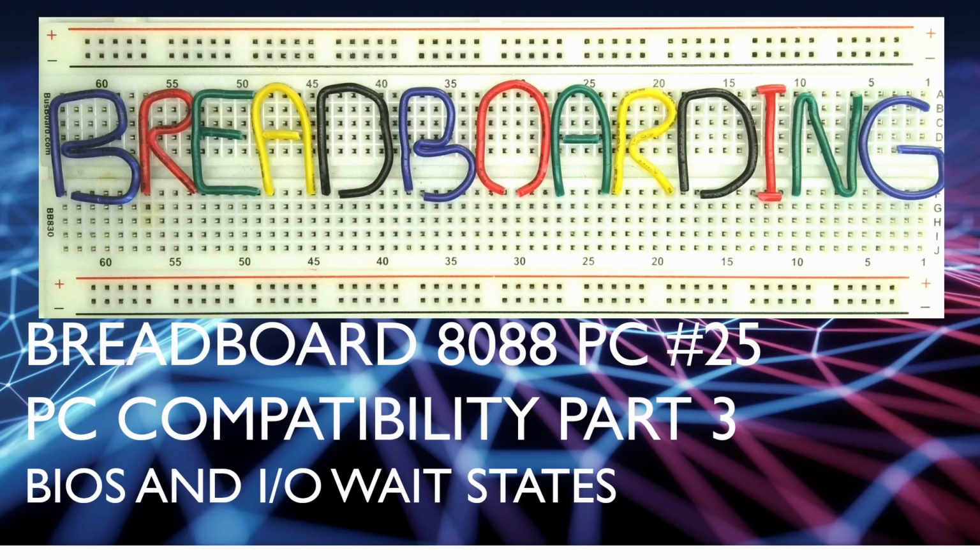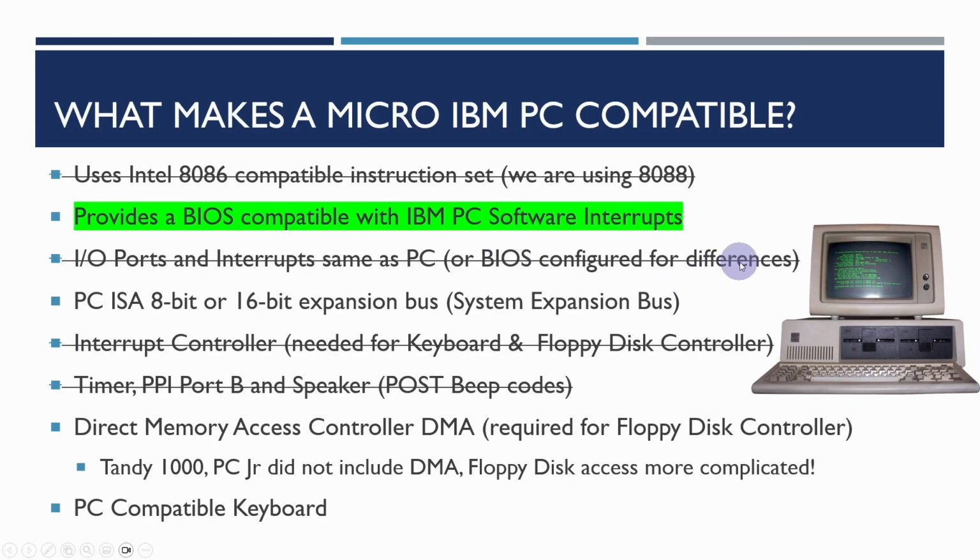Welcome to Breadboarding. This is video 25 in the Breadboard 8088 PC series, and this is part 3 of looking at making our micro PC compatible, where we'll be building the BIOS and also looking at an issue to do with the timer and I/O wait states. Providing a BIOS compatible with the IBM PC software interrupts is the main thing in software we need to do to make a micro IBM PC compatible.